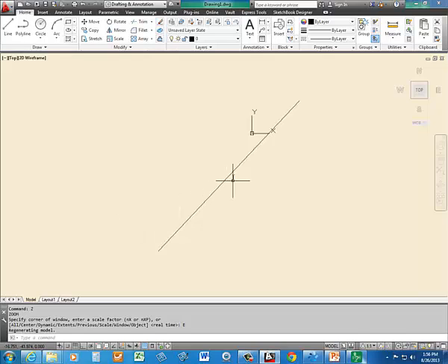So just draw each line with its own length and bearing, and I would draw them just out in space somewhere. Don't worry about connecting them, and then move them, connect them endpoint to endpoint, and see if they all connect nicely. And you'll have to make a decision on some of it, where there's a gap, you'll have to decide which one is more accurate.